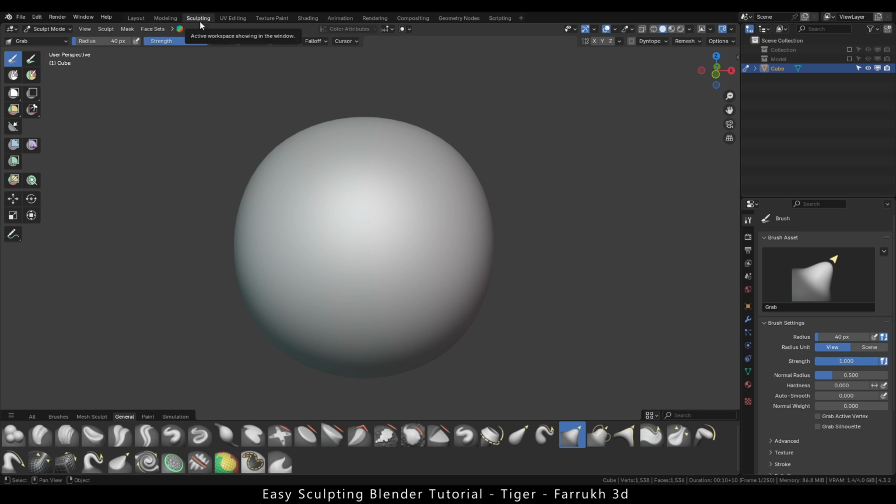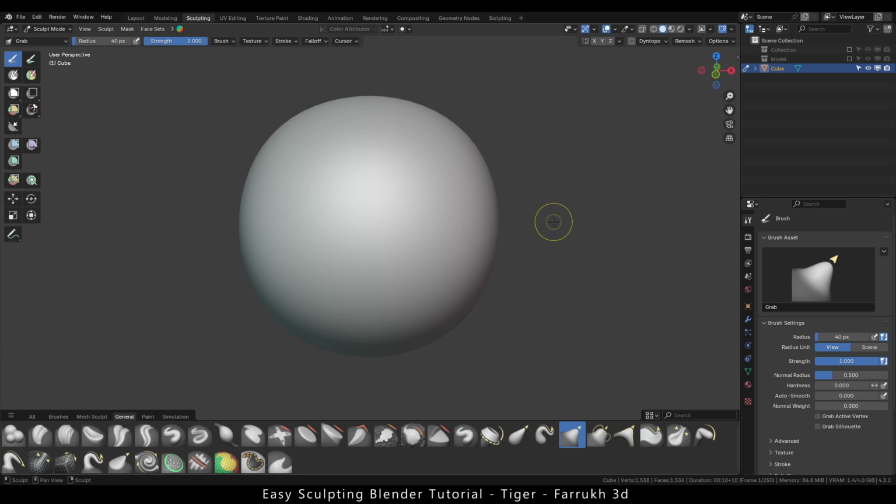If you are using a new version of Blender, then you will be able to see the sculpting brush assets in the lower side. Some settings that we will do before sculpting. Turn off fast navigate. In the remesh, enable fixed poles and turn on X symmetry so both sides are updated during sculpting. You can change the brush size with F.